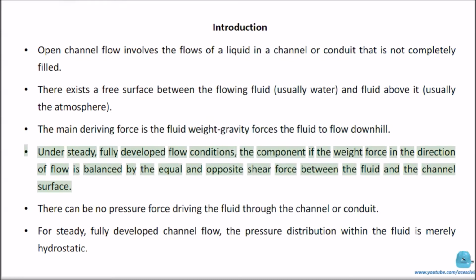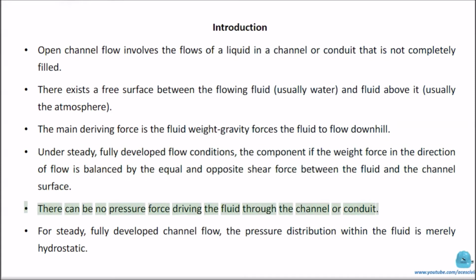Under steady, fully developed flow conditions, the component of the weight force in the direction of flow is balanced by the equal and opposite shear force between the fluid and the channel surface. There can be no pressure force driving the fluid through the channel or conduit. For steady, fully developed channel flow, the pressure distribution within the fluid is merely hydrostatic.